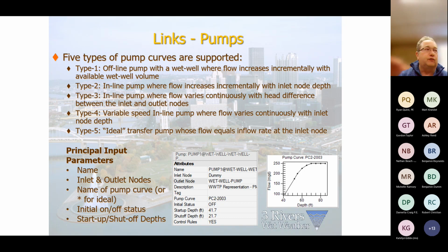Other times you may want to just put a composite pump curve in, depending on the unique nature of each one of those. Most of the pump stations that are in the model now already have pump representations in there. If it is a municipal pump station, you can take a look at those. If there's been changes to how those are operating, that could be something that could be looked at and modified.